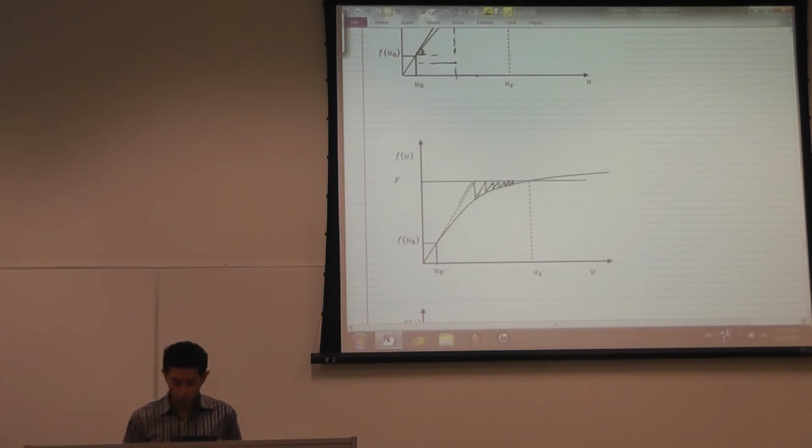Now, this will use way more iterations, but it might be faster if calculating the stiffness matrix or inverting it takes a lot of effort. You calculate the inverse once, and once you calculate the inverse, you just keep multiplying it with a new increment. Depending on the software, this option could be there or not, but this is called the modified Newton-Raphson method.